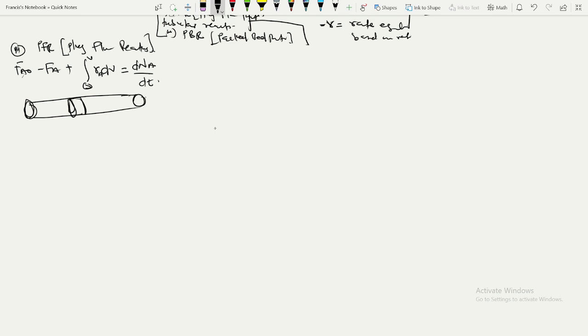So if I consider just this volume, then I can see that at each point in this volume, the rate wouldn't change. And if I consider this point and this point, the rate will change because there is no stirrer here. And with the continuous stirred tank reactors, because there is a stirrer, there's always a stirrer in the continuous stirred tank reactor, that stirs the components present in the reactor. So always there is a uniform rate in the reactors. But with the plug flow reactors, we can't say the same for that, right?